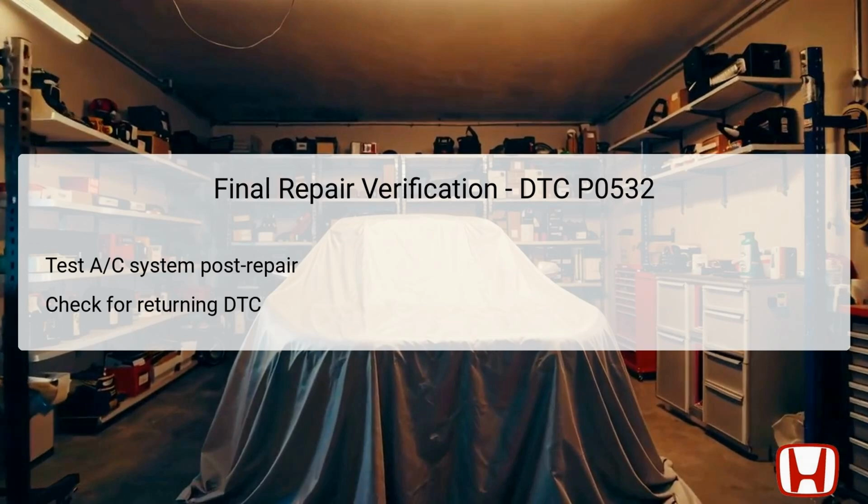Start by testing the AC system to ensure that it is functioning correctly and producing cold air under various load conditions. Monitor the AC pressure sensor to confirm that it is now providing accurate voltage signals to the PCM. This can be done through a diagnostic scan tool or by using a multimeter to check the output of the sensor while the system is operating.